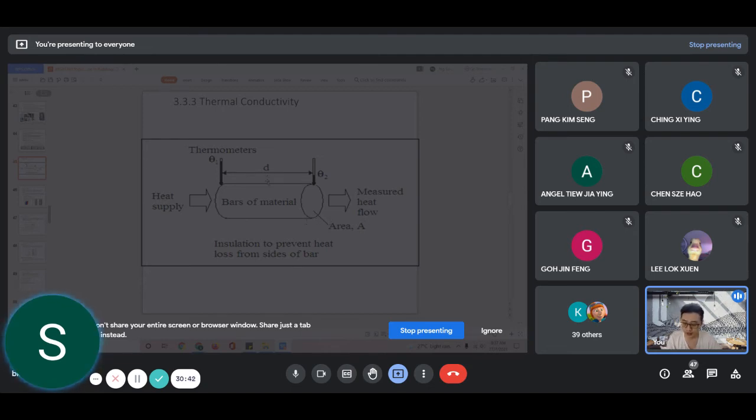So typically, when you have a high temperature here, if the heat is supplied here, it will heat up the material and the heat will travel from high to low. And once it reaches here, if the temperature here is low, it will go out. So with insulation, we have a material in place to ensure that if there's a high temperature here, it doesn't heat up this material and spread the heat into the building. So this is the idea in heat insulation.